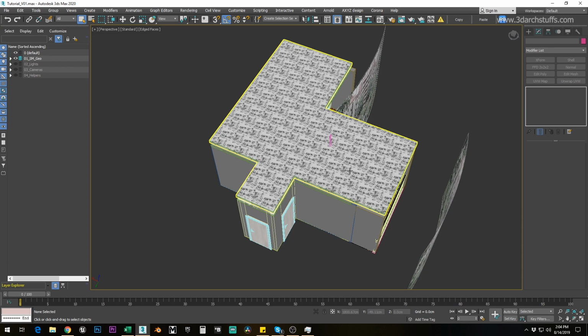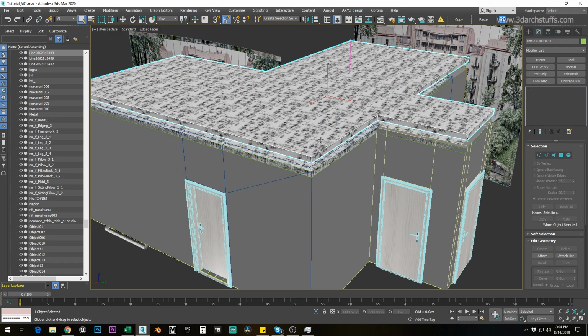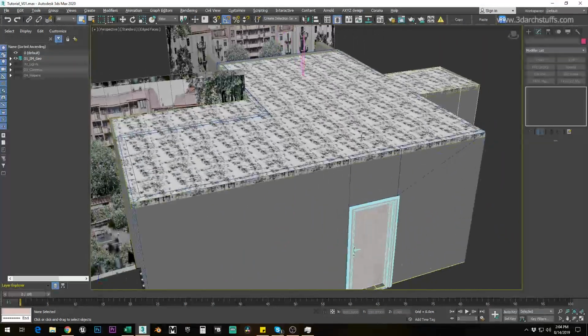So to achieve a high quality, realistic light map bake on every object, we can use two ways. One, we can use a large light map resolution on objects, or we can break the objects into smaller pieces, so a low amount of light map resolution is more than enough to get a very high quality light bake on the objects. So to achieve that, we'll just delete this roof because it's extra and we don't need that thing.